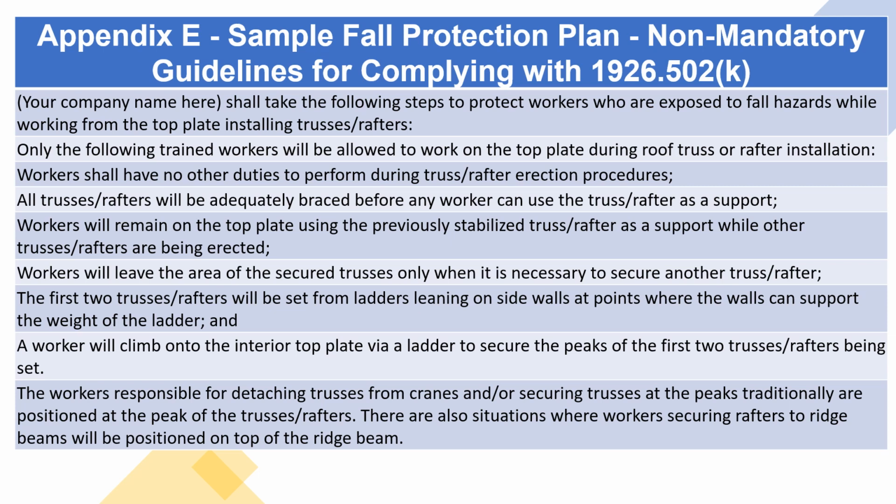Only the following trained workers will be allowed to work on the top plate during roof truss or rafter installation. Workers shall have no other duties to perform during truss/rafter erection procedures. All trusses/rafters will be adequately braced before any worker can use the truss/rafter as a support. Workers will remain on the top plate using the previously stabilized truss/rafter as a support while other trusses/rafters are being erected. Workers will leave the area of the secured trusses only when it is necessary to secure another truss/rafter.